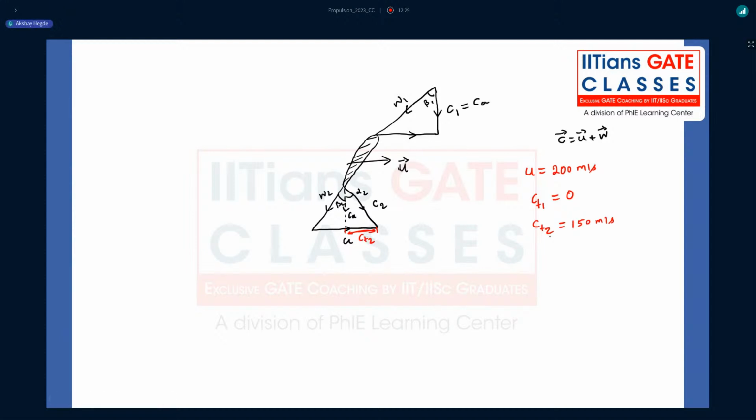So they are asking you to calculate the temperature rise in this stage. I have at the entry T01, and at the exit of the stage I have T02. The actual exit of the stage comes after the stator, but the stator we know is only an energy transformation. So for an adiabatic flow assumption, T02 should be equal to T03. So if we calculate T02 minus T01, that is the rise in temperature in the stage. That's enough, right? So how can we relate it?